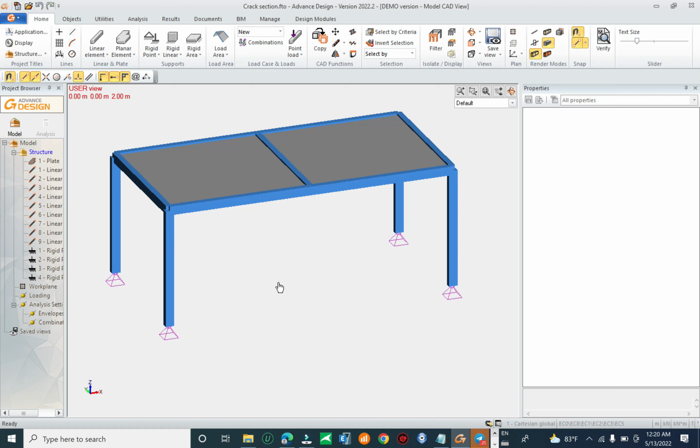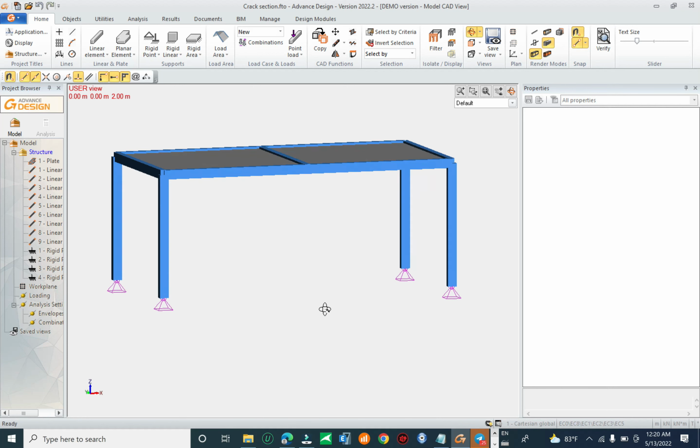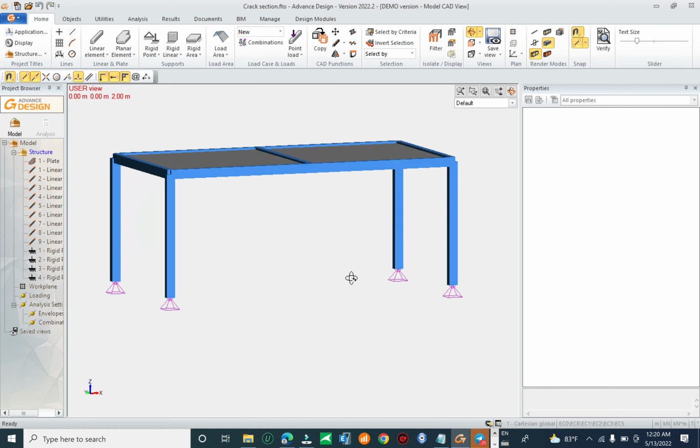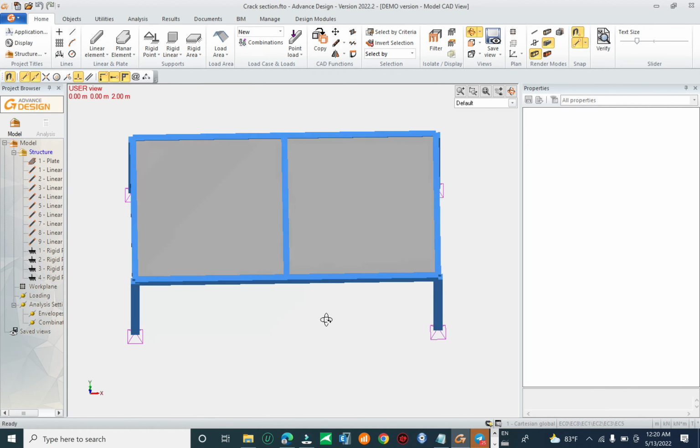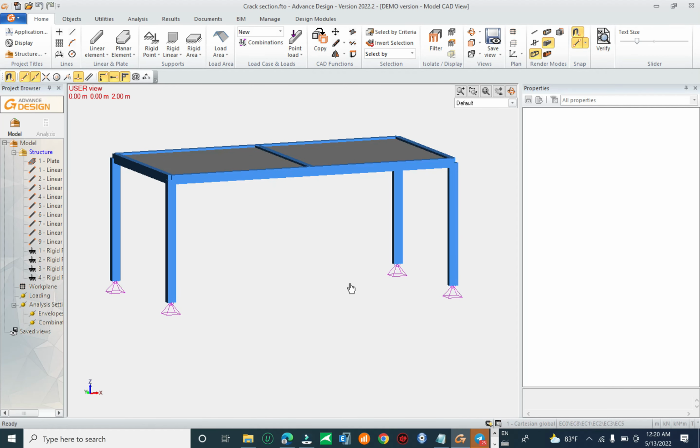So you have to design for the crack section, for the high-rise building and for the tall building. This is a good and complete concept. You apply the global imperfection, local imperfection, and include the modifier for the thickness of the property: thickness for the strong axis, thickness for the weak axis, by using the crack section.